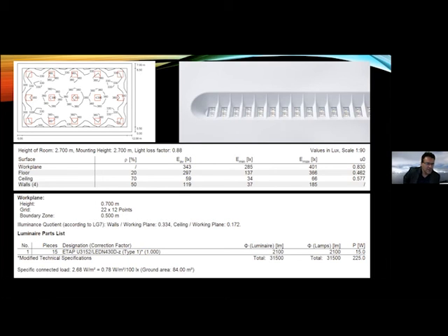0.88, if you can use it in the office, you definitely should, unless you're dealing with a very dirty environment. We're maintaining at our work plane 343 lux, which is relatively close to 320. Uniformity is quite good. And the key point is that you can deliver 343 of the maintained illuminance burning around 2.7 watts per meter squared. Okay, that's the key figure for designers and for people who are designing green buildings. You want to keep this figure as low as possible.